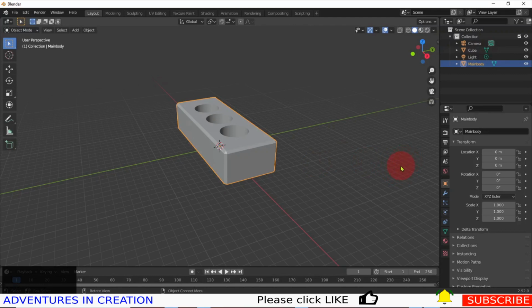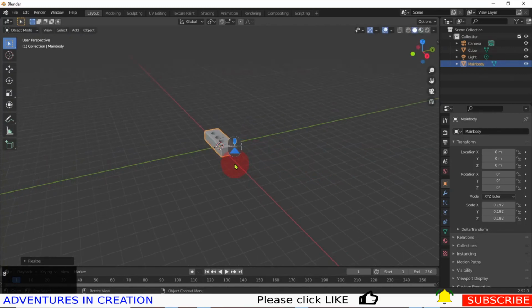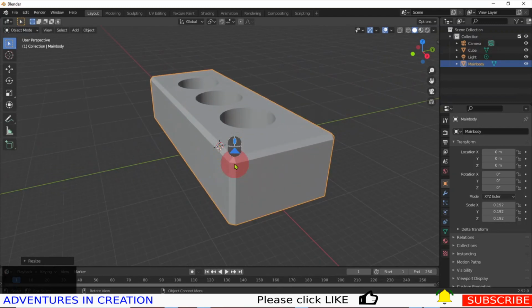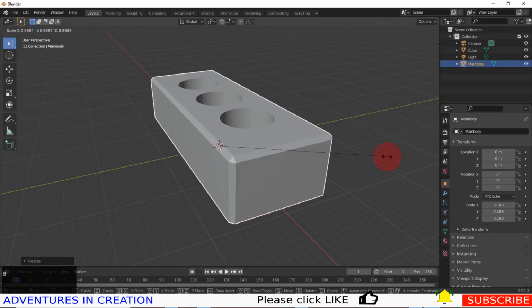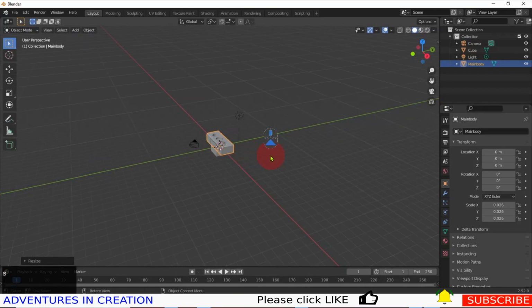So I'm going to scale it down. To scale it, you just hit S, and then you just move your mouse, and it will scale. And if you watch in the middle there, well, actually, I'm going to zoom in a bit so you can see a bit better. If you watch in the middle, you'll see the default cube is still there. You see the camera, you see the lights, you see how massive this thing was when it came in.